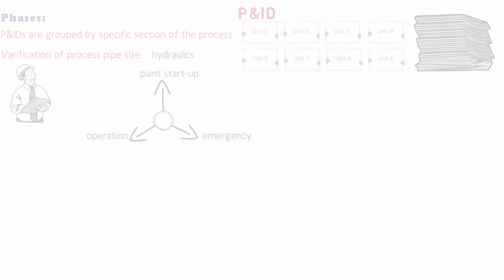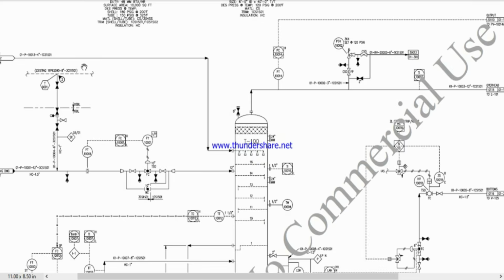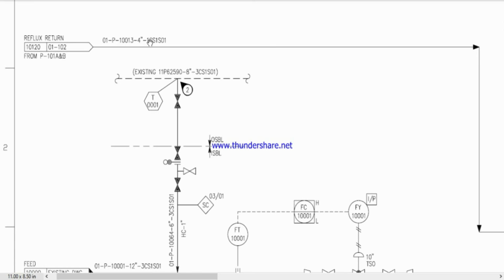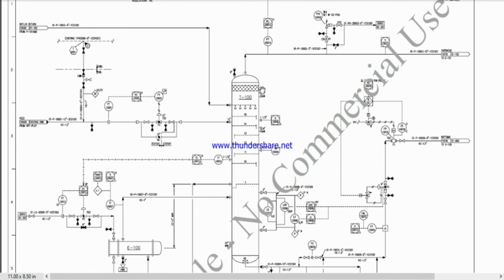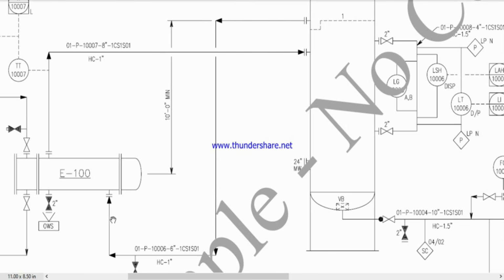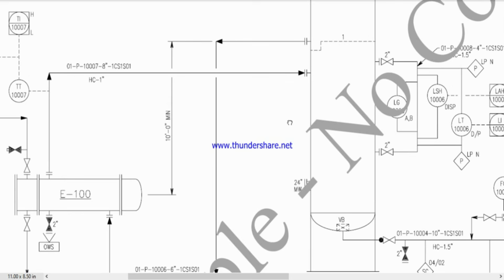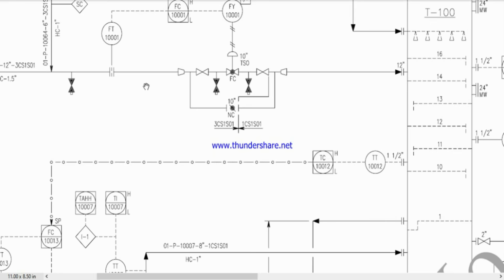At this stage, the process engineer must consider the terminal points for all the pipes shown in the P&ID so that each individual pipe can be given a unique identity known as the line number. In a very simple case, a pipe runs from one equipment item to another with two terminal points without a branch connection. This simple case presents no difficulties, but in the majority of cases found in practice, common problems arise in case of the following. Pipe changes specification between equipment items.